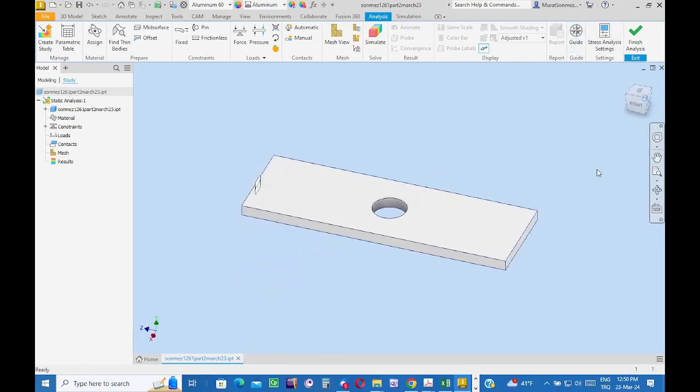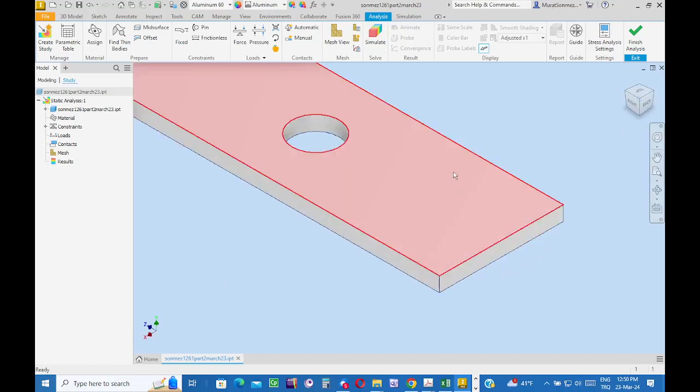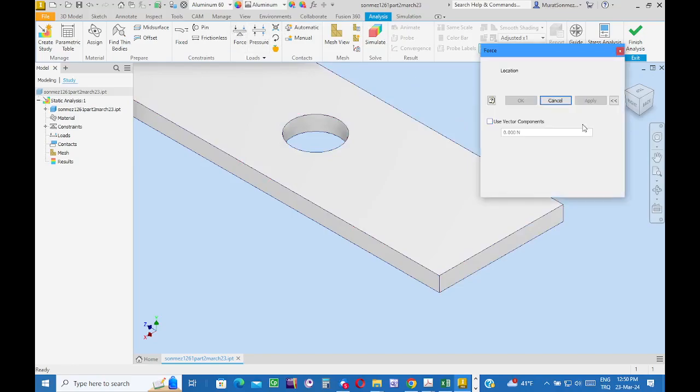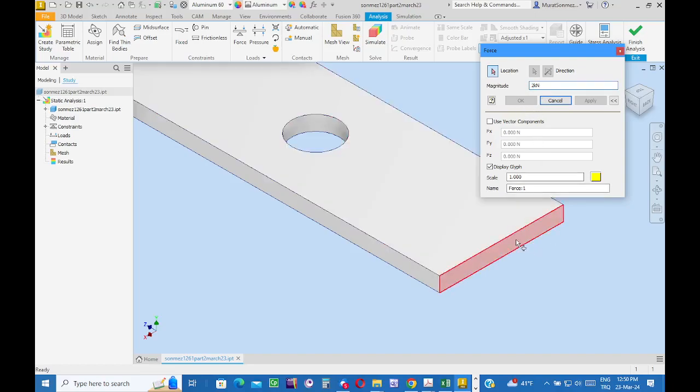At the other end, here in the example, a distributed load. Clicked on this button. The magnitude of the load is 2 kilonewtons. Okay, and that is the surface. It is not a pushing but a tension type load. Reverse the direction and then say okay.